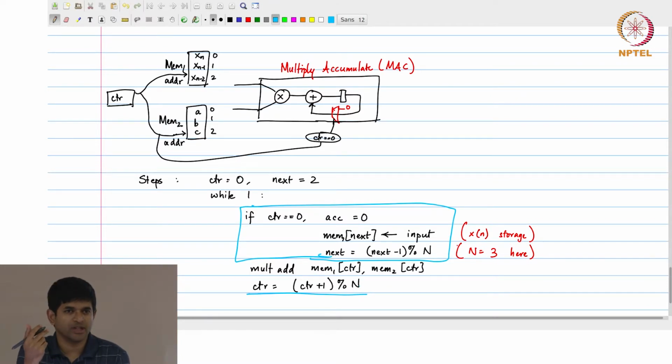What we are doing over here is, in hardware it's very easy to implement a shift register. The moment we start thinking about memory blocks and software, shift registers are no longer very efficient, because shift registers involve moving a large amount of data around. Every piece of data needs to move into an adjacent location.